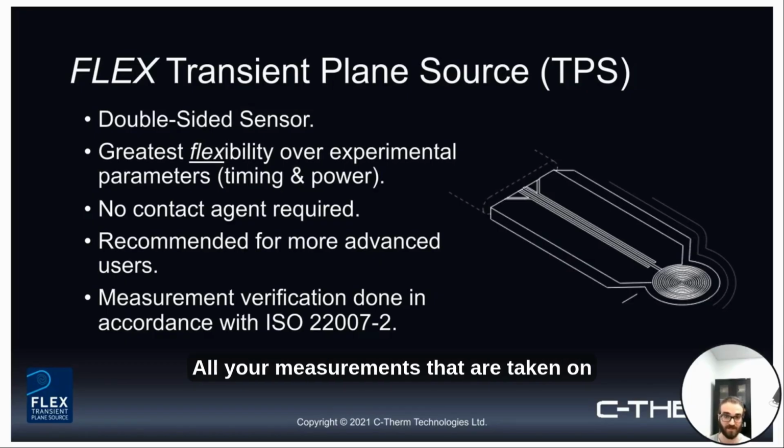All your measurements that are taken on TPS, you will go through a verification process, which is done in accordance to the ISO 22007-2 standard. Again, of course, looking at the TC kit, there will be some slight differences in conformity based on the TC kit TPS versus the Trident TPS, which was briefly illustrated in that opening video. But again, the way you go about verifying and validating your results will be quite similar.